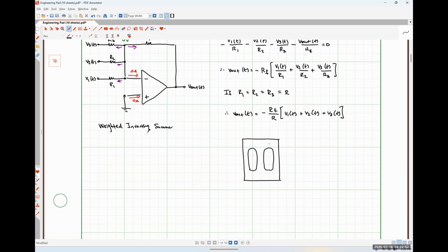Each of these places where I'm supposed to put my feet has what's called a load cell. There's one for the ball of my foot, and there's one for the heel of my foot. And each one of those load cells generates a very small voltage, usually on the order of a few millivolts for every pound that is placed on it.